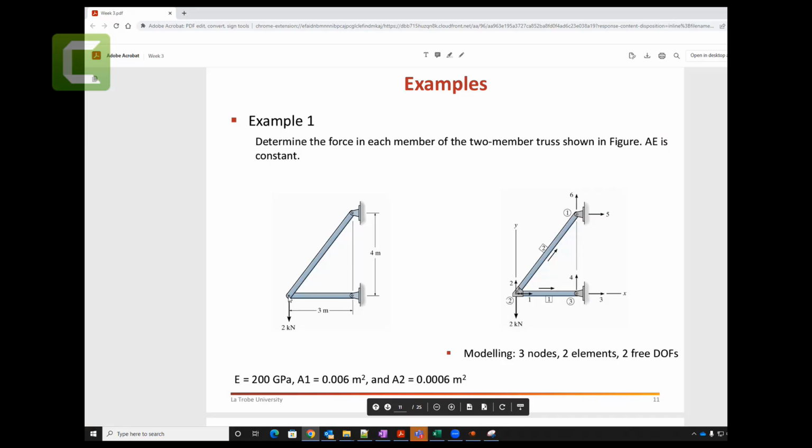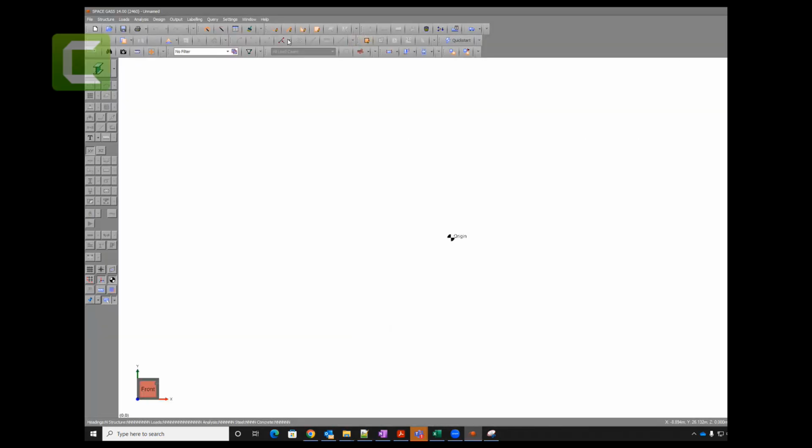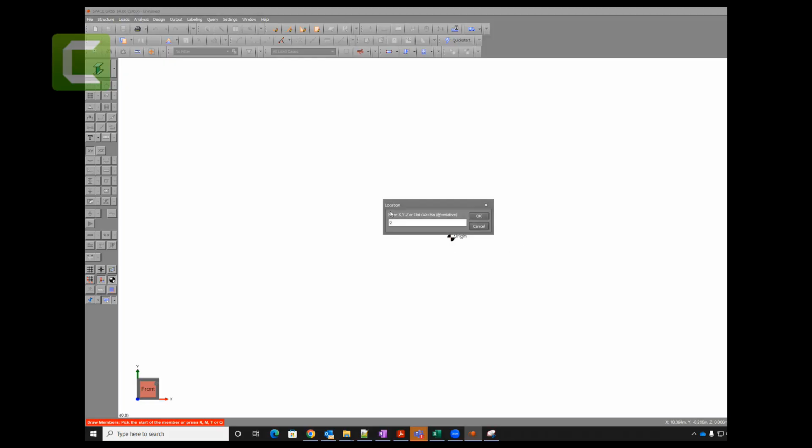So you agree with me that if I want to draw this one from 0, 0, then what you do is you go here, draw members. Click on draw members. Don't press anything on your keyboard. Sometimes you may pick something else, but it has a highlighter. You can pick it, but I generally don't do it. I press 0 on the keyboard.